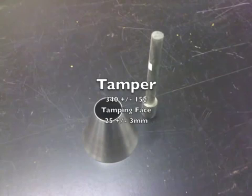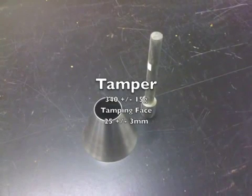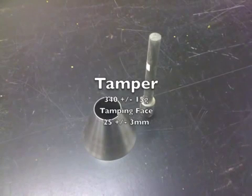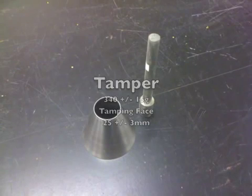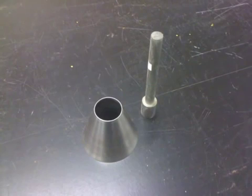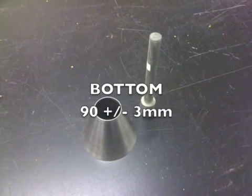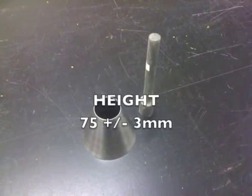We do this with a mold and a tamper. The tamper weighs 340 grams plus or minus 15 grams, while the tamping face must be round and flat with a diameter of 25 millimeters plus or minus 3 millimeters. The mold is in the shape of the frustum of a cone with the following dimensions. The inside diameter at the top shall be 40 plus or minus 3 millimeters, while the inside diameter at the bottom shall be 90 plus or minus 3 millimeters, and the height will be 75 plus or minus 3 millimeters.